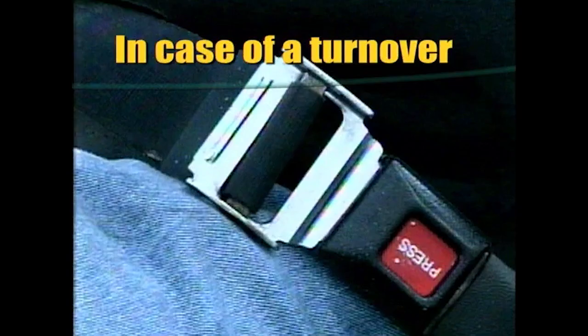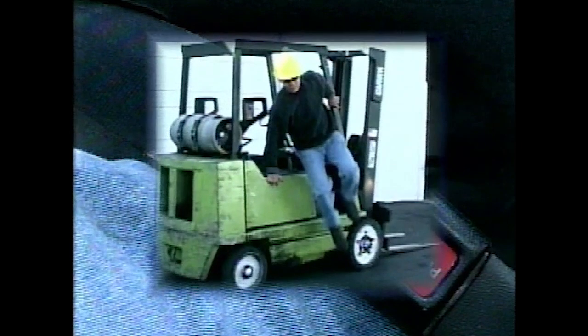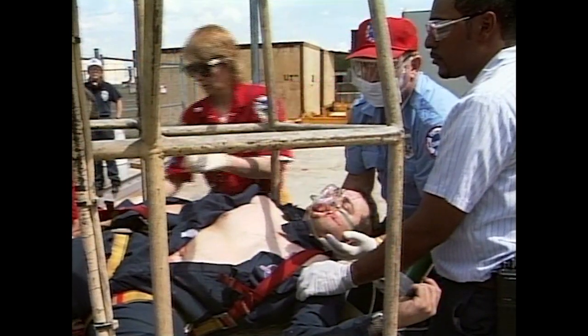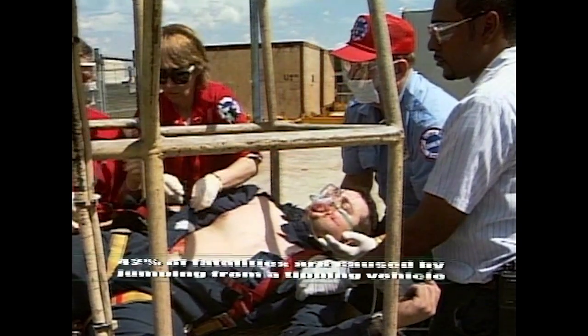The ITA states that studies on forklift turnovers usually result in minor injuries if the forklift operator stays with the vehicle instead of jumping off. The normal tendency is for a person to jump downward so the driver lands on the floor or ground, usually directly in the path of the overhead guard. In a tip-over of a sit-down truck, the operator should lean away from the direction of fall to minimize injury. The most common result in a tip-over, where the operator jumps out, is a crushing injury to the head, neck, or back where the overhead guard strikes the operator.